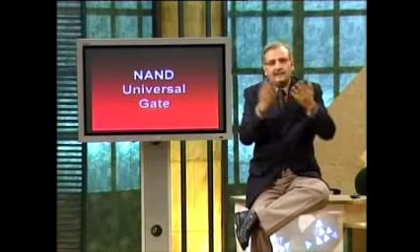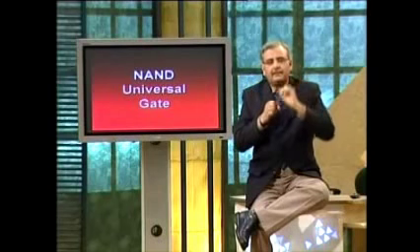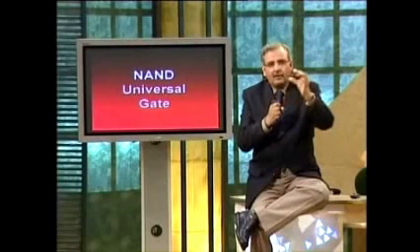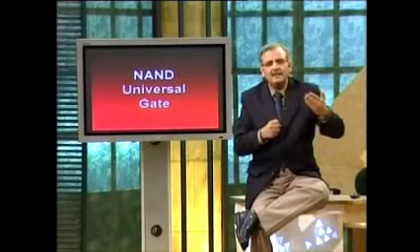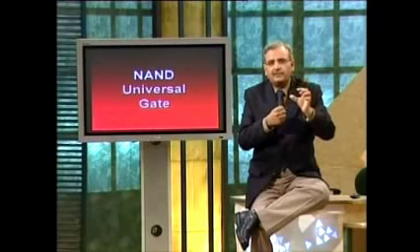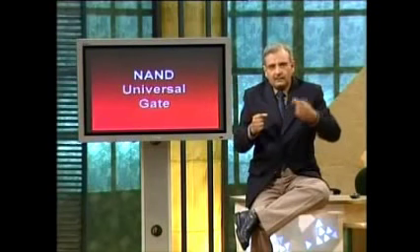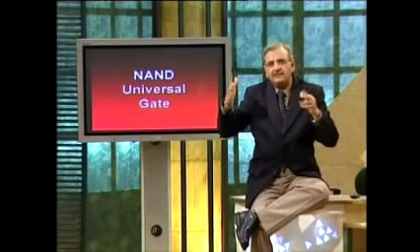Let's look at the OR gate symbol. The OR gate symbol is of course the closed V lying on its side. The alternate symbol which represents the OR gate is the AND symbol. On all its inputs and outputs, you put a bubble. Bubble, what does the bubble mean? It means inversion is happening, right? So let us see what this alternate symbol for an OR gate represents. It means 0 and 0 should give you a 0 output. Right? Now, if you just remember or you look at the function diagram or the truth table of the OR gate, when do you get 1? If any of the inputs or all inputs are a 1. If both inputs are a 0, what do you get? The output is a 0. So this is what the second symbol represents.